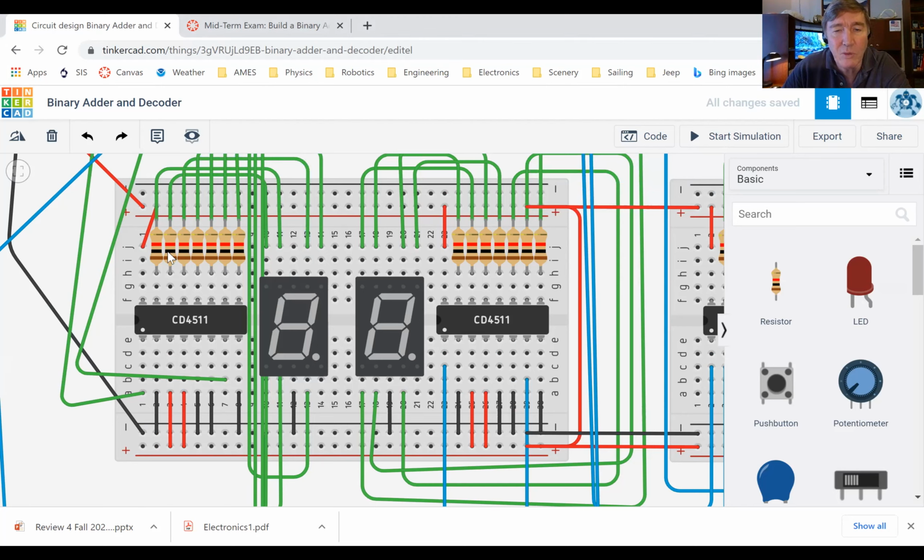I recommend to use a 1 kilo ohm resistor, because if you don't, then you're going to have too much current. You're going to destroy it. Okay, and then these pins down here, these are your inputs. So you can see this is input 2, input 3, and this is just a lamp test. You just make this one be always high. Just have 5 volts go into this one. And the one that says blanking, just make that one always be high too.